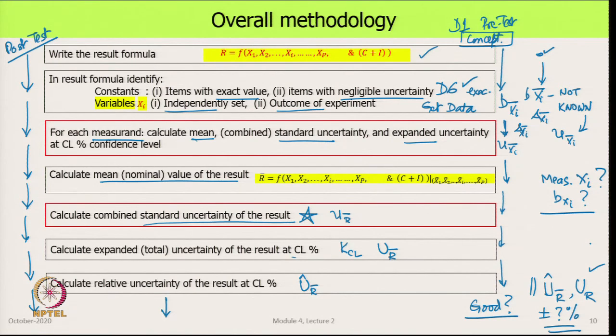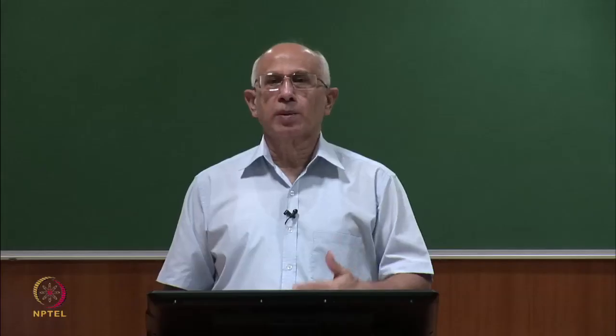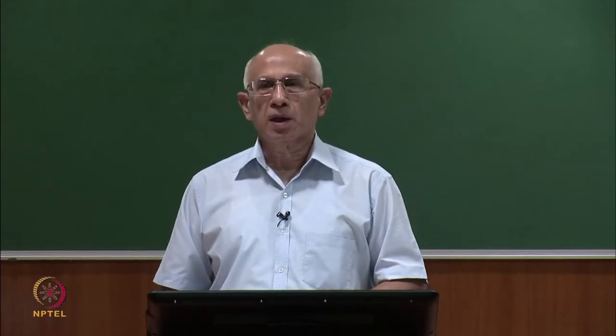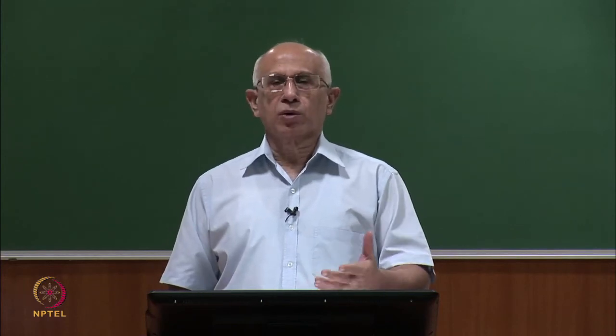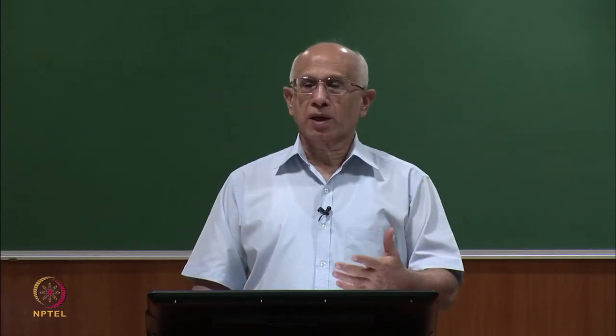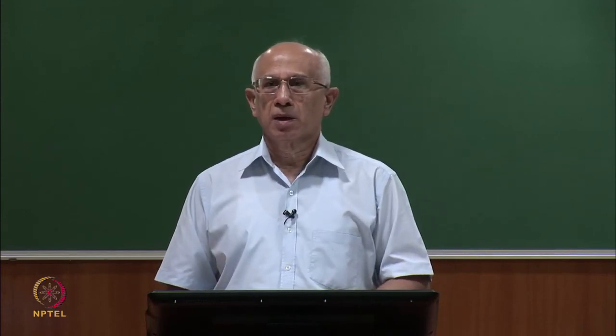And there could even be a case that if this was specified, we had a result formula and we had all the instruments that we have, so we knew all the bxi's, we could calculate beforehand and check whether this mandated uncertainty in the result is achievable or not. There have been instances where somebody said, I want this thing to be tested with so much percentage uncertainty. Do you have a setup? And we could say, look, I have a setup, let me check what uncertainty I can get with my setup.